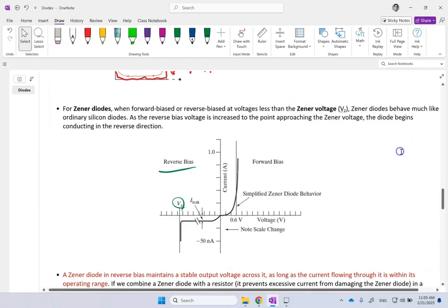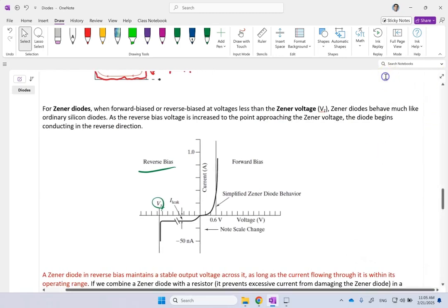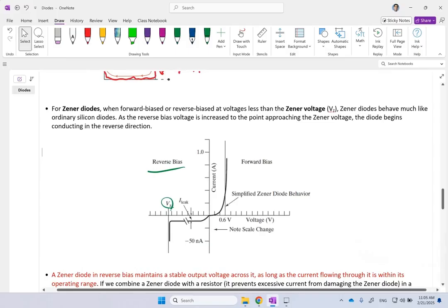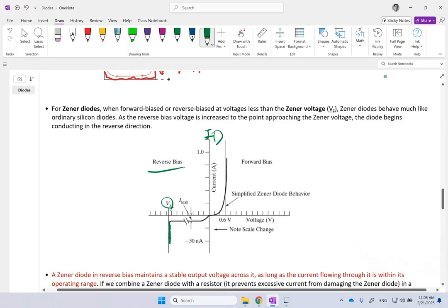After that, it kind of surrenders completely, gives up, and allows the voltage to fully pass and shows literally zero resistance. So if you look at the voltage-current behavior of the Zener, you see that it kind of goes like that. And you see your current starts increasing without any more increase in the voltage that you need to apply.